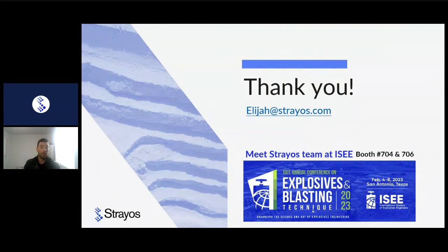Yeah. With the pre-splitting, understanding, like we talked about, the site conditions, what kind of rock you're dealing with, and if there was any test drilling done prior, gathering that information so when you start drilling those pre-split holes, you know how that rock might react and how to adjust. That way you don't drill a large amount of pre-split and then come to understand that it either deviated or was drilled at the incorrect angle.